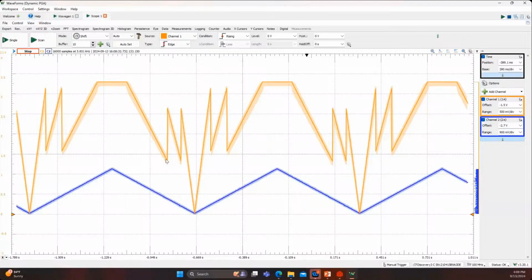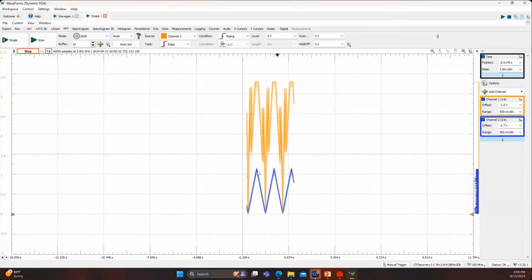Then you will increase the gain, which will then increase the op-amp output. Follow the same process until you then hit the maximum programmable gain, which is 32 for the MSP op-amps, and continue to decrease until you hit 0 volts. Then the process repeats again and again.